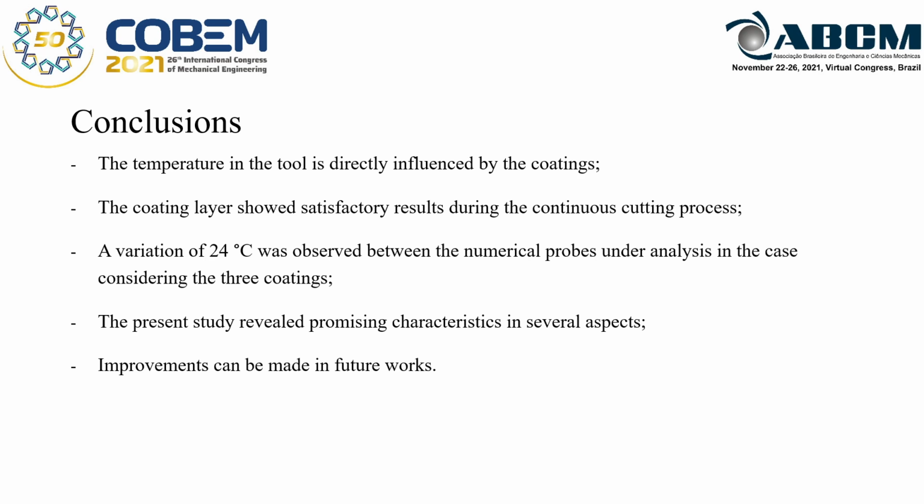Also, the studies carried out showed that for a uniform heat source with time variation, considering a surface of constant contact between the chip and the tool, the temperature in the tool is directly influenced by the coatings when the thermal properties of the coating are different from those of the substrate, even for a thin coating of 10 micrometers.